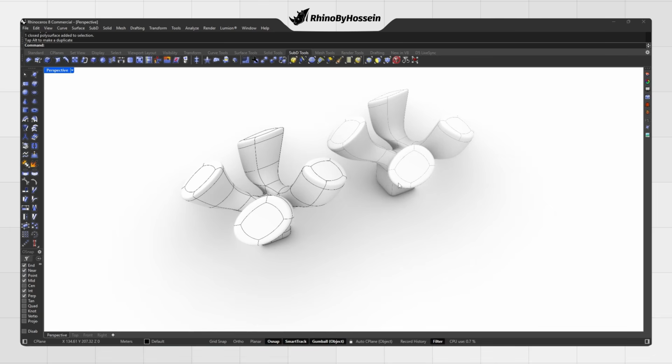However, there is an important point to keep in mind. When a SubD model is converted into NURBS, its structure changes. Instead of a simple and flexible SubD model, we usually end up with a large number of individual surfaces. Because of this, converting too early can make the model much harder to manage. It is usually better to complete all major form adjustments inside the SubD workflow and keep the conversion to NURBS for the final stages.